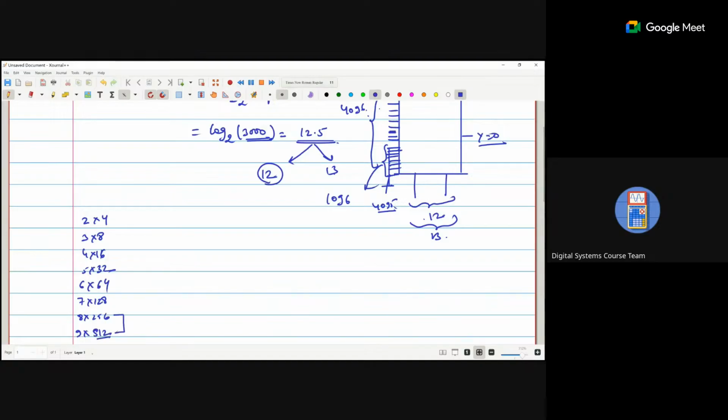The output lines, 496, lie between 256 and 512, so we use a 9 input line decoder. We get 512 output lines, out of which 496 are used as they are and the remaining are connected to ground. So how many input lines are required? 9.